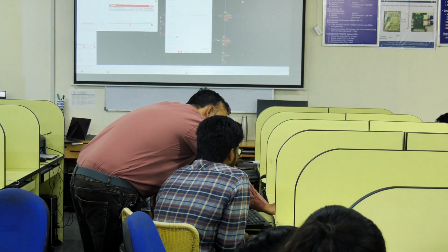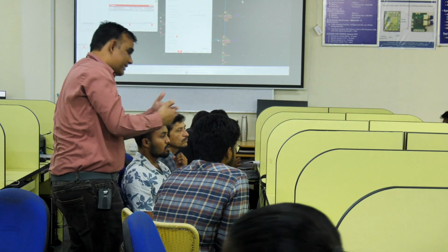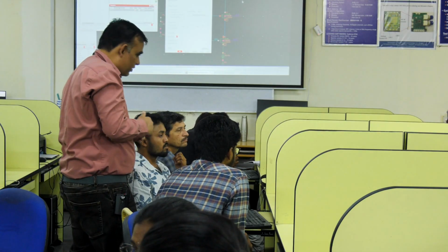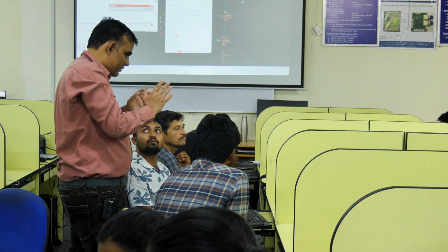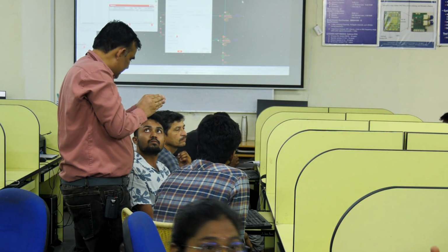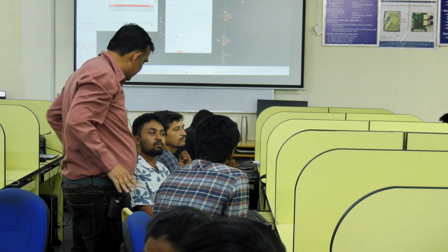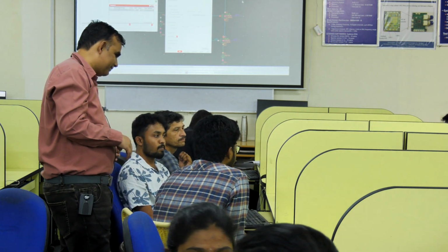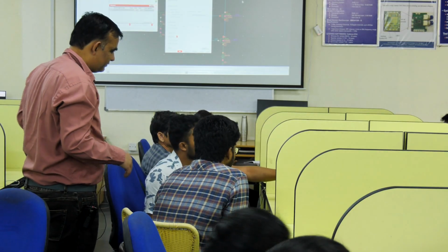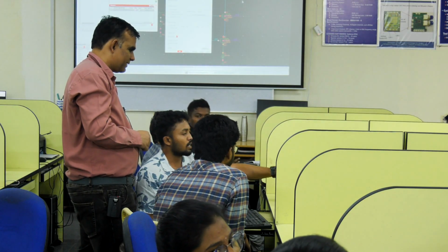Yes, yes. Now I have these three of this, these three of this. Can I place both of them on one side so that they take less space, and this side there's nothing there? Yes, yes. Should I place them in the corner, side? Should I place them in an L-shaped corner? Or many times what we do is we first put the transistors and then say, okay, this is the smallest area in which we can put the transistor. My diode has to be, my pixel has to be 5. Whatever is left, I fill it with diode. It doesn't matter if it's 2 micron or 3 micron or 2.75 micron. Okay? To the neighboring pixel.